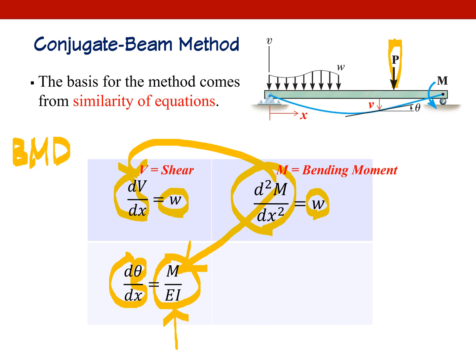And I is the cross-sectional resistance to bending. So EI, if you have both of them, represents how hard it is to bend. You can increase either E or I to make your beam stronger, or both. Anyway, E is a material property and I, moment of inertia, is a cross-sectional property. Memorize it, very, very important and fundamental.